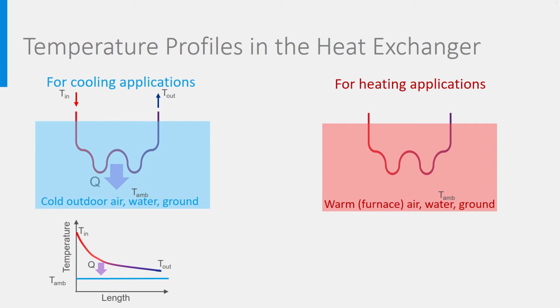Maybe you expect the reservoir to become warmer, which would be the case if it was small, but we consider large reservoirs being replenished continuously. Think for example of the sea or a large lake or just outdoor air. Please pay attention to the fact that the temperature at the cold side of the pipe is always higher than the temperature of the reservoir. It cannot cross the light blue line. There is a temperature difference needed to exchange heat.